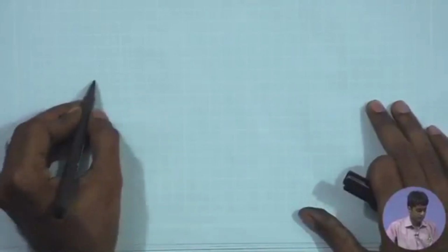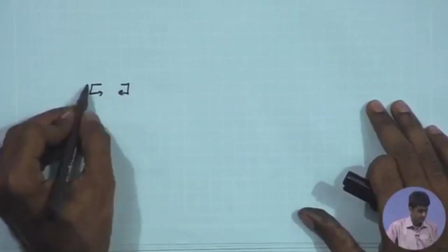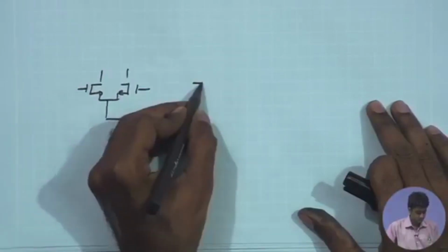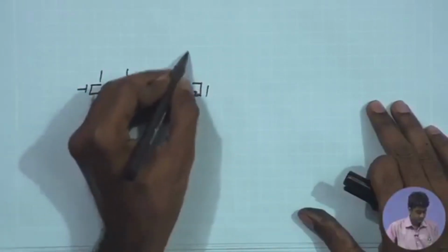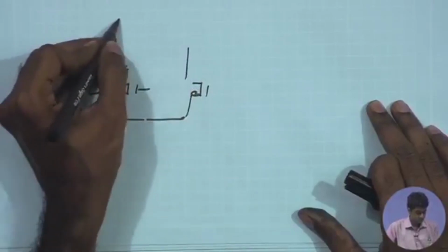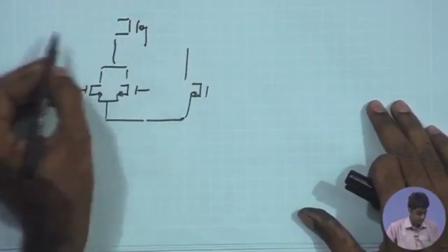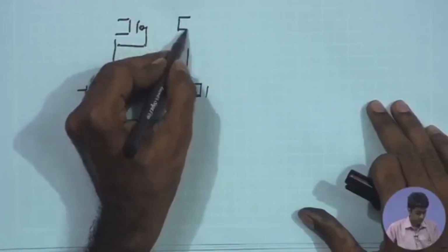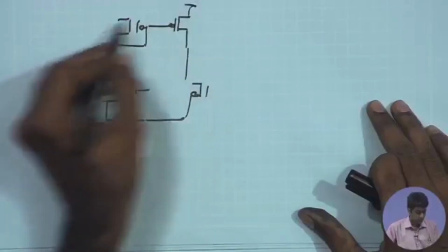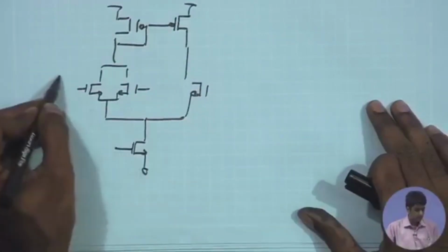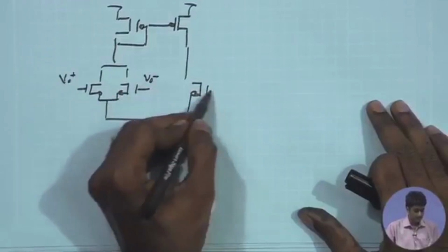So, one of the important points that were discussed in the simulations also is related to the input device dimension, the GM of the input device. So, if we are using, say, dual loop common mode feedback where we are relying on the diode connected load, and this is your VO plus and VO minus coming, and this is your VREF.